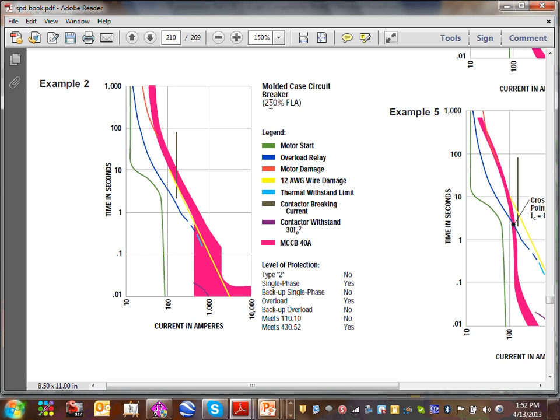They size it like you guys did with Jeff yesterday, 250. Look at the QB. The QB is not even protecting your motor. On the damage curve, if there's heat, it might not even protect your motor windings. These are windings of your motor. If you size it that fast, actually it's not protecting even. Now remember, this is the manufacturer's fuses talking about circuit breakers. So maybe you just be very careful. You definitely will find another circuit breaker that does a better performance than that.